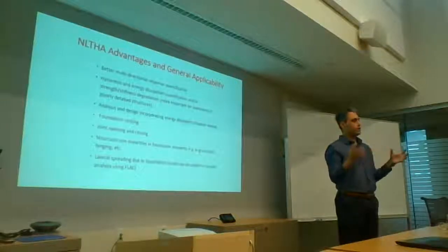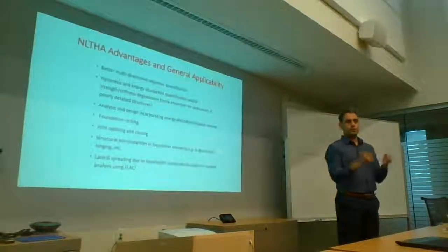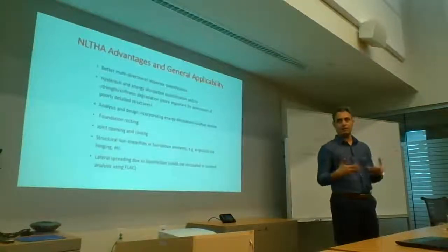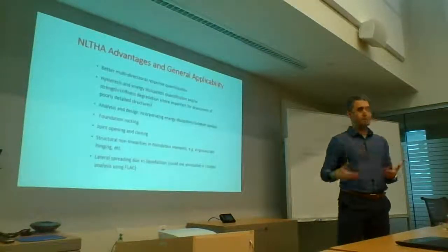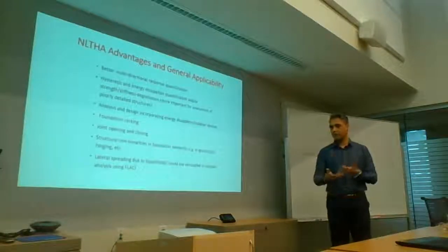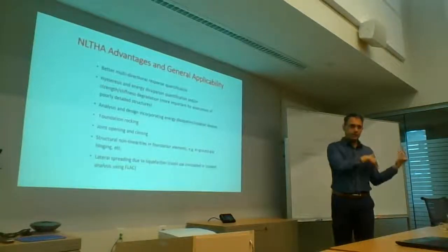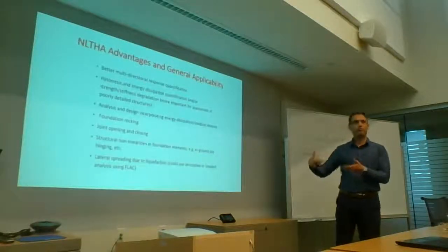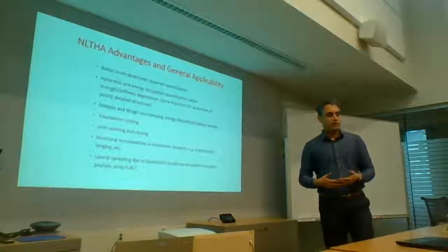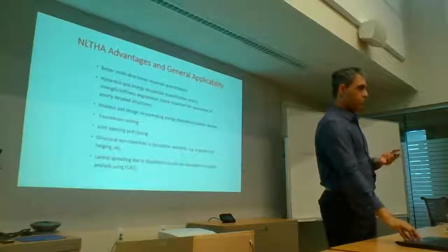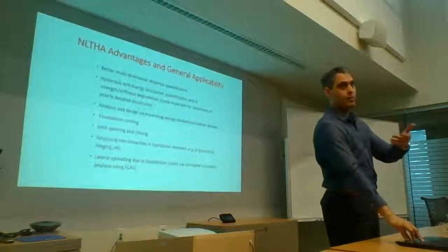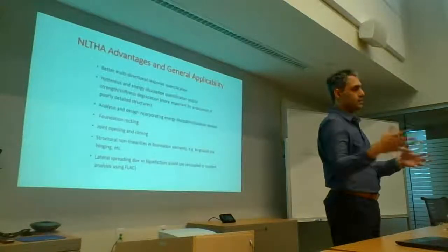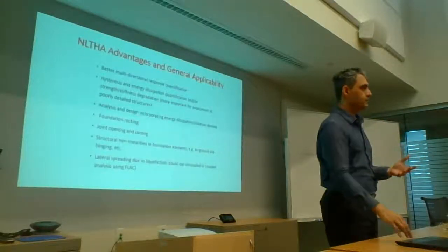So we had to lump column properties and stiffnesses and strengths together and give them a single element for a multi-column bent, etc. Just to get some sort of coupled analysis going and get some meaningful results. Then we had to come out again and use your normal structural software to impose those demands. And then the whole idea is that you detail it properly so that if the soil is moving half a meter or a meter, you're able to take that. Okay.